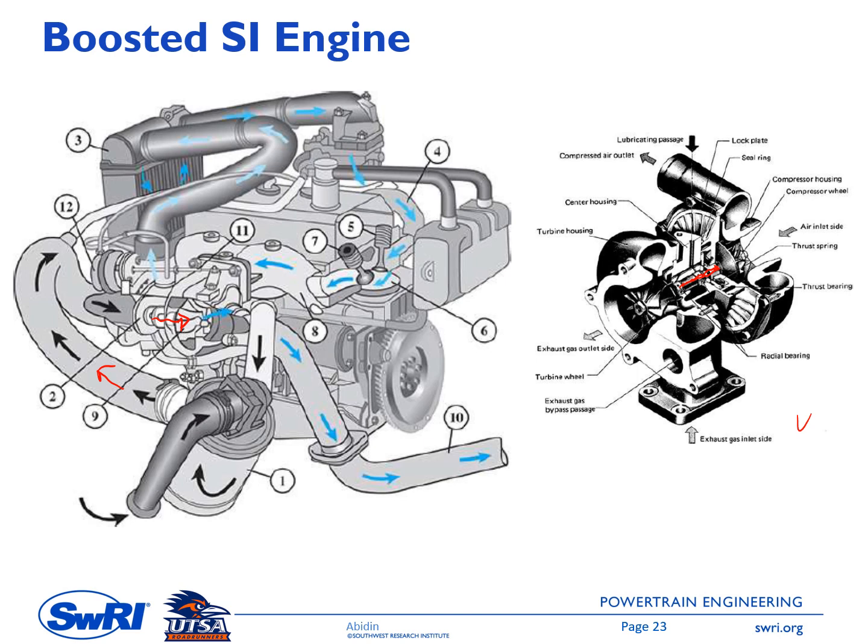Okay, it is going to the engine through this point. So this is the intake runner. You can see in here, before entering the engine, the fresh air needs to flow through this one, and I think one of these components will be the charged air cooler. So the fresh air is cooled to further increase the amount of air entering the engine. You know, for the same pressure, if you lower the temperature, we'll have a higher density.